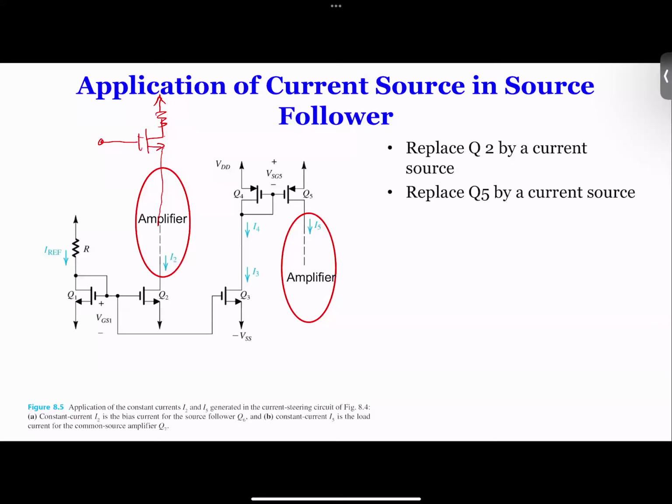We'll simply have this RD and V1 here, and we have VGS, which in this case is the input voltage. So what type of amplifier do you have? Well, it's not certain yet, because we have input at the gate and output at the drain. So this is a typical common source amplifier.